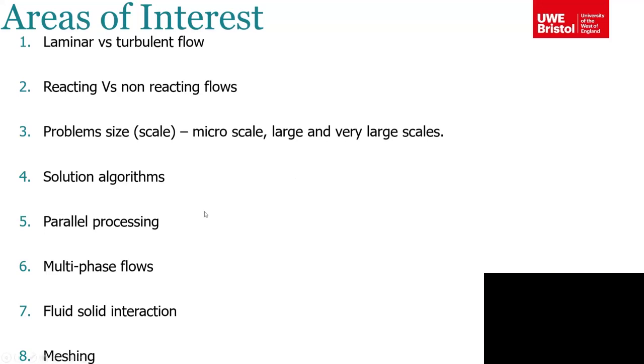And you will be looking at different solution algorithms which have different times to solve, and then you need to look at parallel processing as well. You already use parallel processing, so when you give the command to the computer to use 4 processors, that means parallel processing. Usually it's a power of 2: 2, 4, 8, 16, 32, 64 and so on.